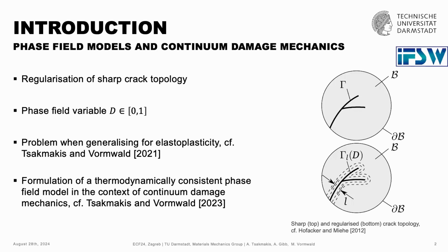Now, since I already stated that the starting point was linear elastic fracture mechanics, there's an obvious problem when we want to generalize this in order to capture a ductile fracture phenomenon, since obviously we are missing the information on the plastic deformation within this model. And it's really not straightforward to generalize this model. There are lots of approaches in the literature. And what came to our mind is to essentially make use of already known things. For instance, continuum damage mechanics is known to offer a very convenient framework for exactly those types of phenomena.